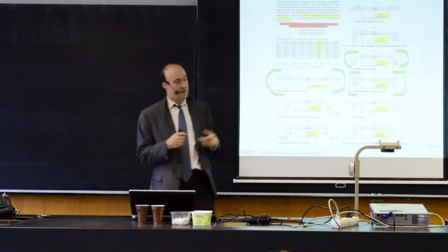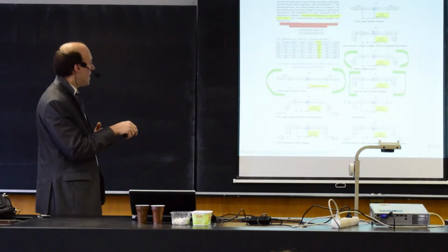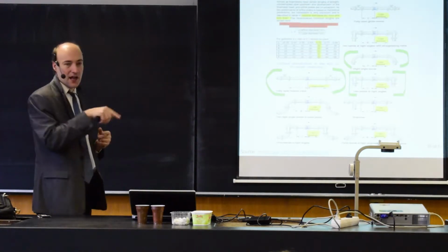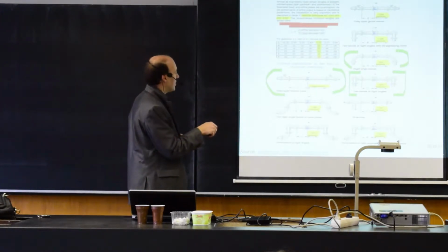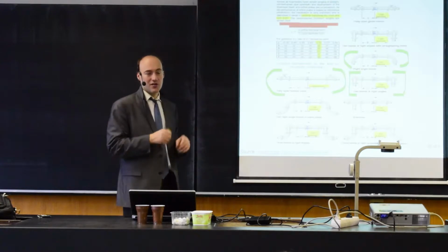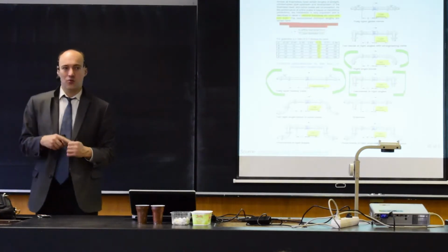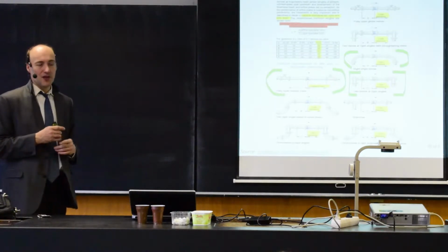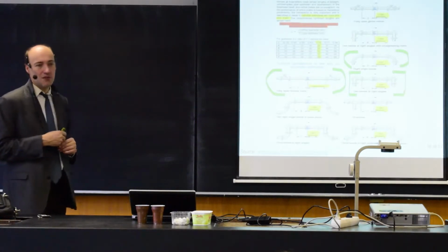If you have something in front of the orifice plate, such as a bending, for example, here we have an orifice plate, we have a bending of 90 degrees, then we need to keep 29 pipe diameters. So again, it's a lot. For large pipe diameters, if you would have 50 centimeters, for example, pipe diameter, you would need to have 50 times, let's say 30, so 15 meters.